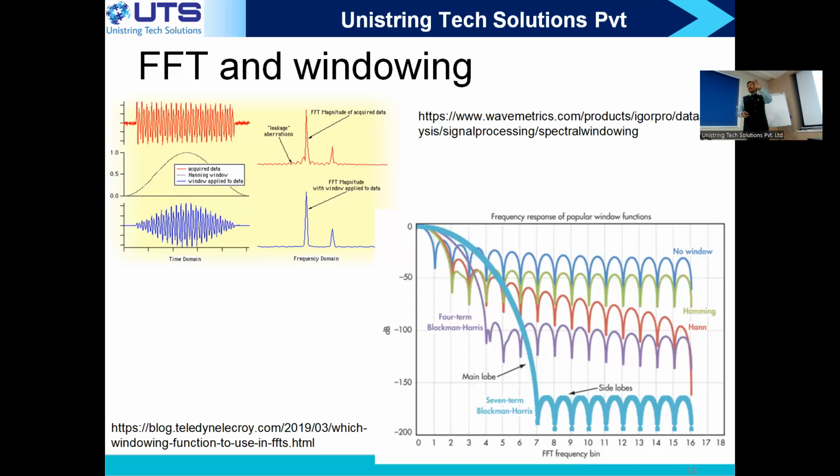The eigenfunctions in your fast Fourier transform equation, X[k] equals x[n] times e to the power minus j omega n, are so selected. They're called kernels, or eigenfunctions in signals and systems. They are such that whatever correlates with the eigenfunction at this bin will have nulls, in the sense that they correlate very poorly in the adjacent bins.